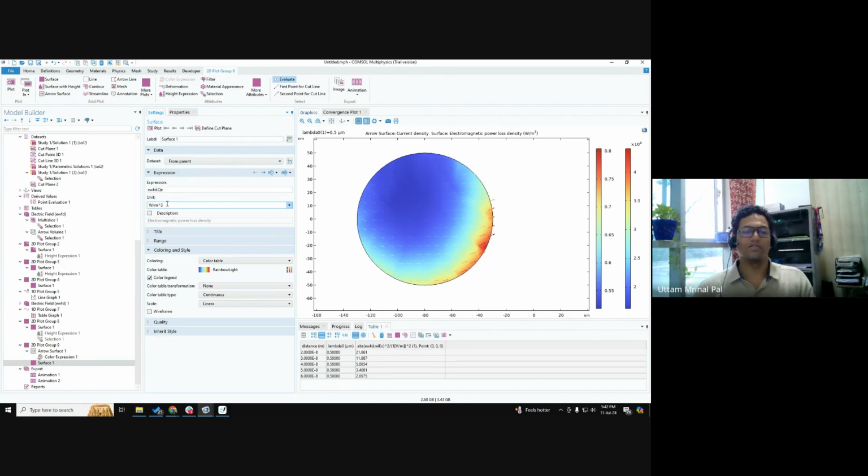This is the part of the multiphysics node that I wanted to cover. Multiphysics is because you want to couple these losses, and you can take these losses into heat transfer. You can add a physics, and then you can see what is the rise in temperature on these nanoparticles, and you can quantify how many degrees of rise there is if it is switched on for some time. You can also see how much deformation there is on these nanoparticles because of the rising temperature, the thermal expansion as well. Okay.